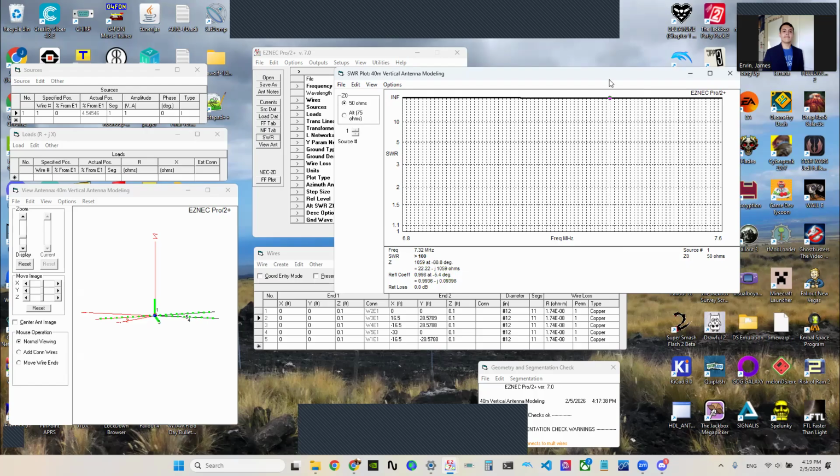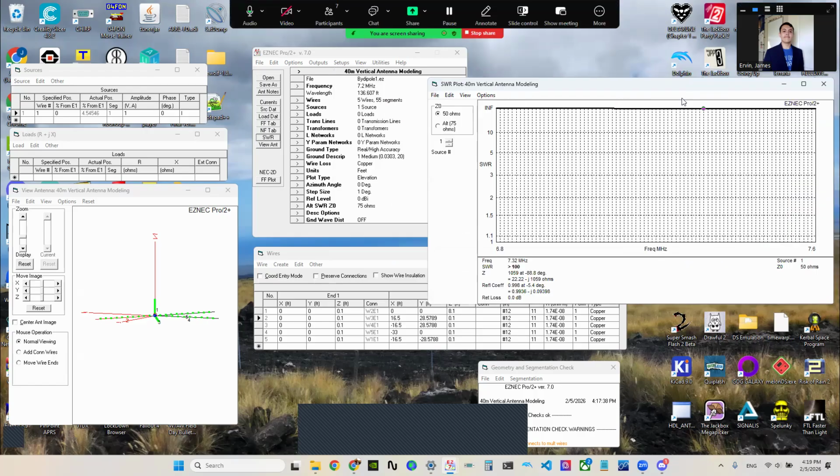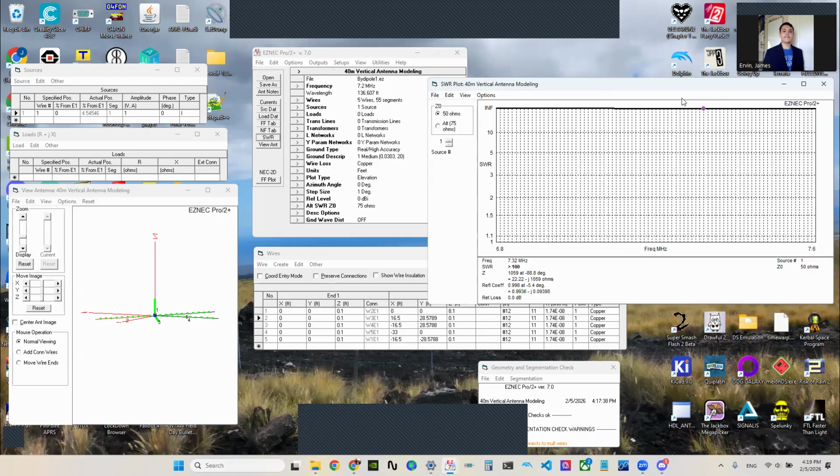So what we're going to do is have a little bit of fun with this, shall we say? We need to calculate an amount of inductance that will cancel out the reactance. So basically, the reactance is down here. It's that, minus j however many ohms, right? So we need to calculate a value of an inductor that will cancel out all this reactance at a given frequency. You can do it with some math, or we can be smart with it.